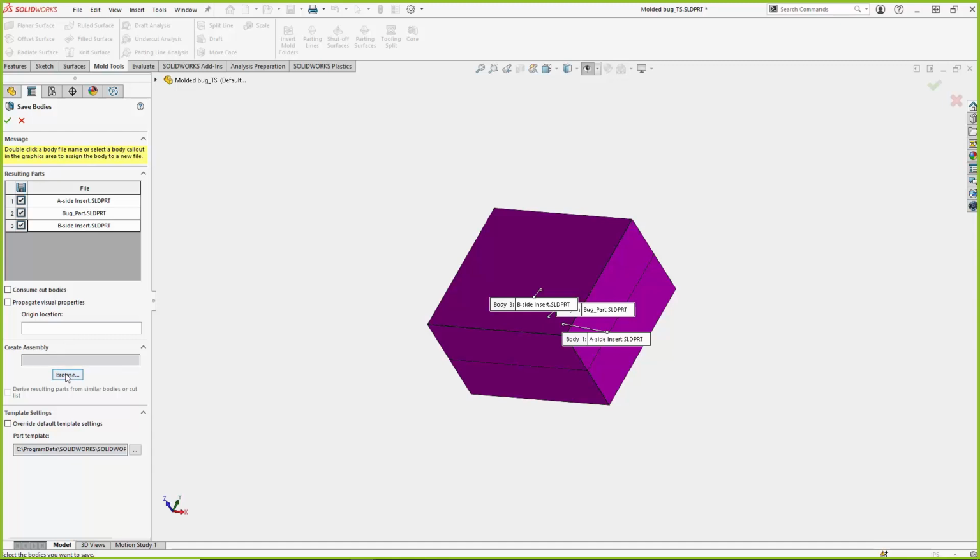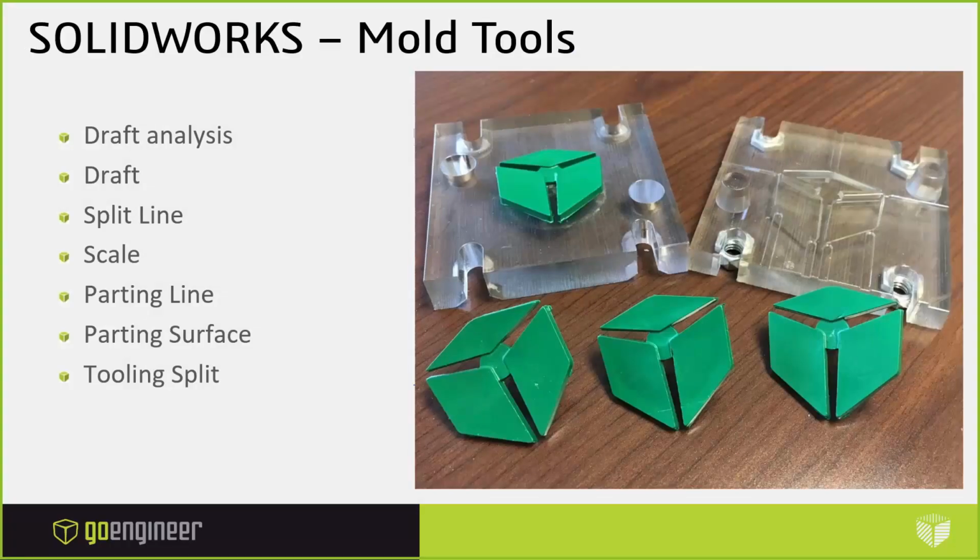I also have the option at this point to create an assembly of all these inserts to start working on. Once I got all of these parts, I took those parts, made some additional cuts, added some guide pin areas, and added some nut holders. You can see I also added little vents in all of that. That's all done through SOLIDWORKS. I then send my SOLIDWORKS file into GrabCAD Print, then print my models out on the J750. So now I have little molds that I can mold my parts with.